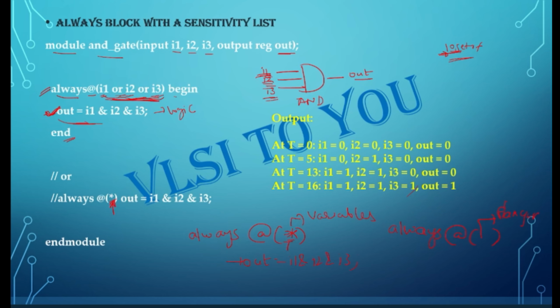Now what happens if you keep the star? What is the difference between keeping the star and mentioning the variables? For example, if you have four variables here, I4 also, but you want your always block to react only to these three values, then any change in I4 will not activate this always block. It will ignore the value since you have mentioned only three values. So any change in the I4 value will not be included in this always block.